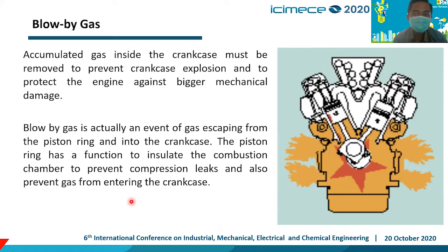Blow-by gas. What is blow-by gas? Blow-by gas is accumulated gas inside the crankcase that must be removed to prevent crankcase explosion and to protect the engine against bigger mechanical damage. Blow-by gas is actually an event of gas escaping from the piston ring and into the crankcase.